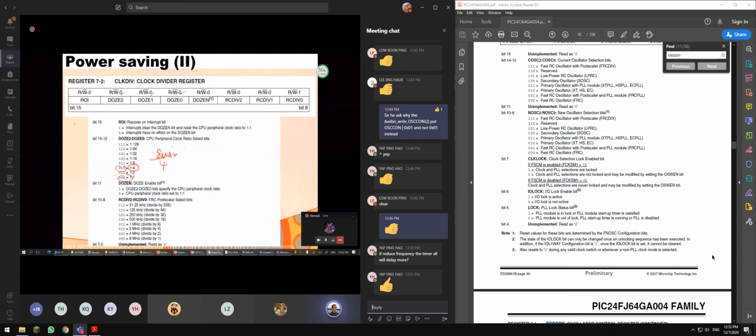Let's say 8 megahertz divided by 4 and divided by 2 again, so it's greatly reduced, then things will become not very accurate when you do calculation. Okay, is it okay? We also got FRC. This is the pre-scaler, post-scaler, FRC post-scaler.